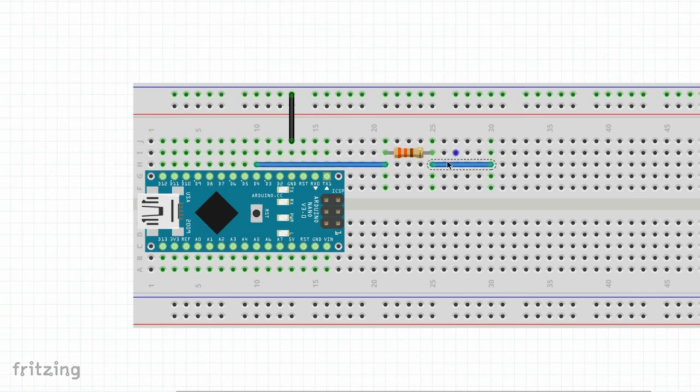Next, I'm just going to add another wire so that I can connect our LED. So I'll add our LED in. Now we have to be careful with our LED because we have to put it in the correct direction. There are two ways of knowing which way is the correct direction. Our negative, or our cathode, has the larger piece of metal inside when looking in, and it's called the anvil. Also, the negative side has a shorter leg, and you'll see this in the labs.